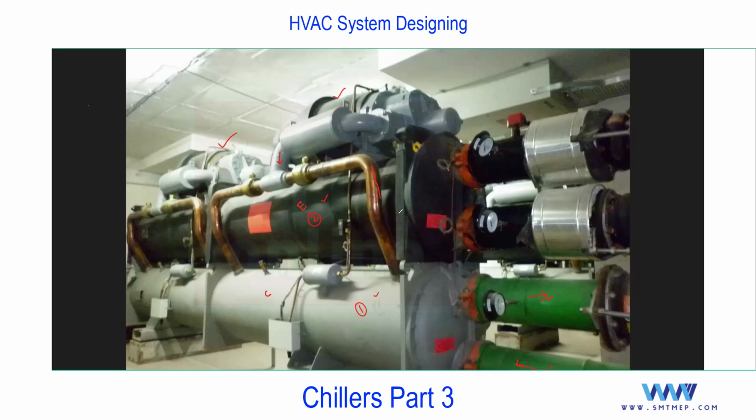So you'll find two shell and tube exchangers, and because of this, you'll find three cycles in this. One cycle is the vapor compression cycle. Same: compression, condenser, evaporator, expansion, you know all this. The second cycle is the chill water cycle, same as air cooled. And the additional cycle in this is the condenser cycle, which will connect to the cooling tower with a separate pump. And why the need for this cooling tower, and how to cool the water which is used to cool the refrigerant, I'll show you with the line diagram.